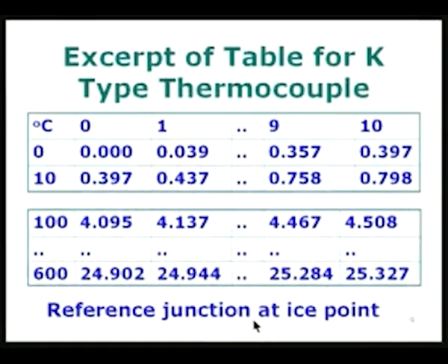One is thermoelectric properties, the second is the physical properties of the material. If the material becomes unusable because it melts or becomes soft and so on, then that is the temperature up to which you can use it. Obviously, for the thermocouple with tungsten and tungsten iridium, the melting point is very high, and therefore we are able to use it up to about 2000, 3800 or whatever number was given earlier.